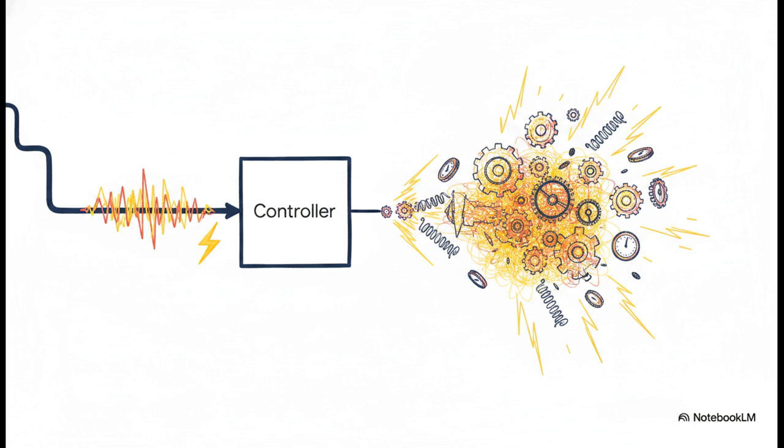But of course, it has a weakness too. Because derivatives measure sudden changes, they are incredibly sensitive to high-frequency electrical noise. If a sensor fluctuates rapidly by just 0.1 degrees because of some nearby electrical interference, the derivative term totally panics, calculating massive erratic output spikes. In tough industrial environments, this term often has to be heavily filtered, or sometimes engineers just turn it off completely.